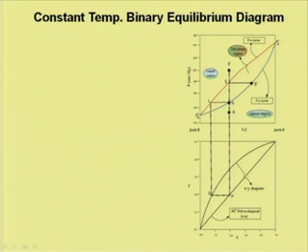corresponding to this point S, the vapor condenses completely. Now, the liquid composition will be the same as the composition of the original vapor, which is at R. If the pressure is raised further, the liquid may be considered subcooled and it will follow the line through S F. The equilibrium composition for the tie line L G is represented by Q P.